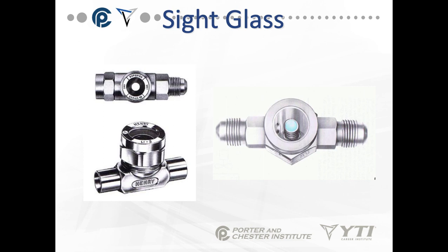Used to be with some of the older refrigerants that we could tell if the system was undercharged by bubbles in the sight glass. This is no longer the case. If you have bubbles in a sight glass, all it means is that there's refrigerant in the system. If there's no bubbles in a sight glass, all it means is the system is either full or empty, because with refrigerant, you cannot see if that sight glass is full. Primary purpose of a sight glass is to check for moisture in the system.